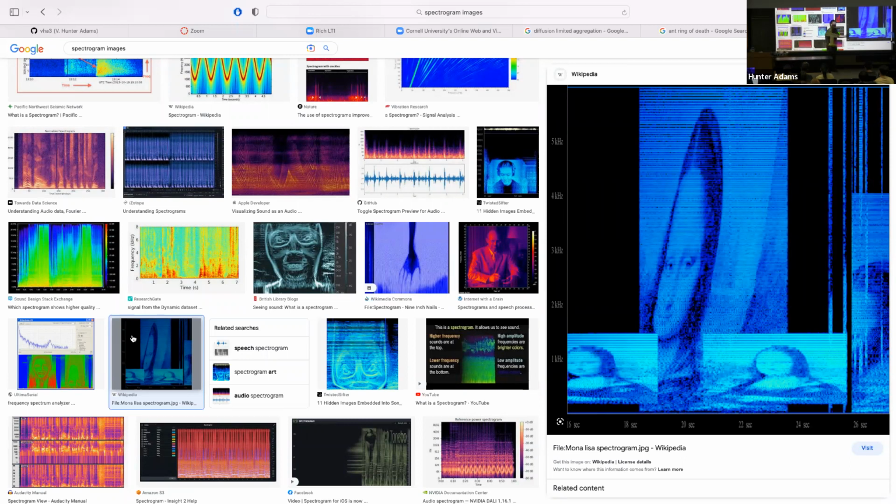Can you generate sounds such that their spectrogram creates images? That'd be kind of cool. You could modulate a direct digital synthesis synthesizer. You can imagine a DDS synthesizer producing one frequency, which on a spectrogram, if it never changes, looks like a line across the spectrogram. If you modulate that frequency into a wave, so it goes up and down, what you would get out is a sine wave on the spectrogram. Could you modulate it to write your name in cursive? Maybe, with the understanding that you can't write backwards, so it gets a little complicated. But maybe you could figure out how to write your name on a spectrogram.